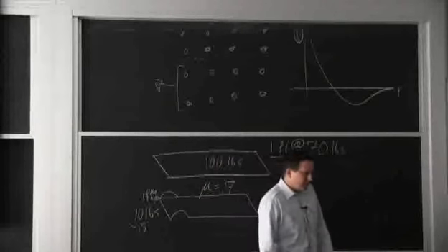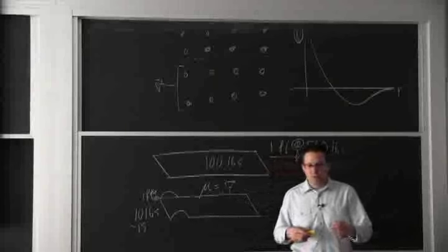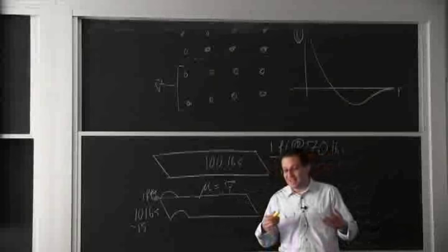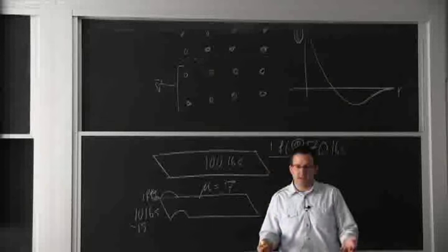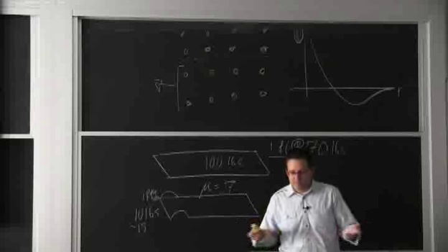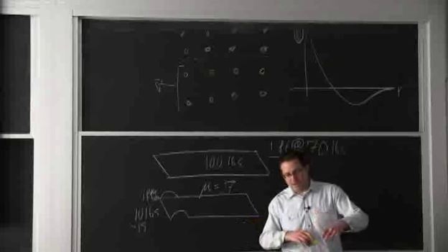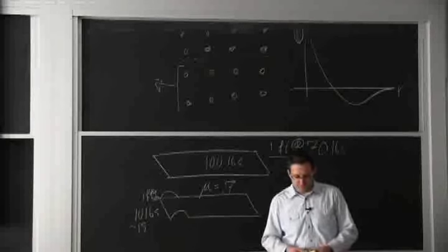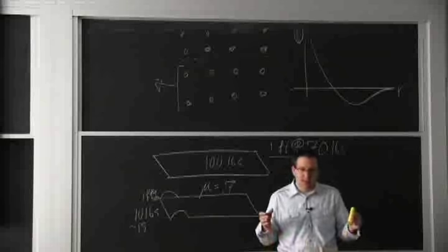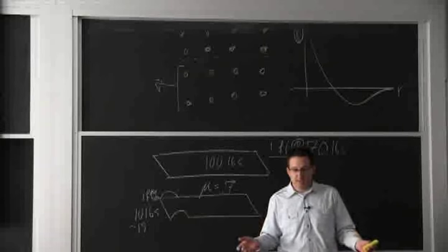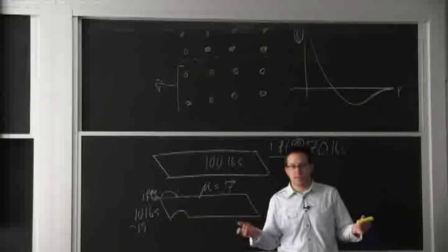So you create that history, you create those permanent changes. Well, they're not that permanent, because you can have an annealing, which is heat treatment at high temperature, that would really remove a lot of the interactions you created, the little knots here and there. The key word would be dislocation multiplication. It happens a lot. And really the way to get them out is to heat up the material.